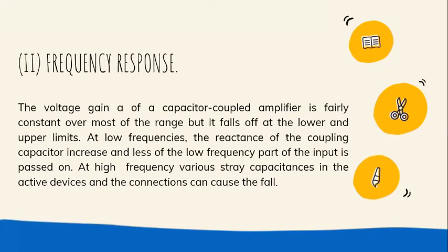At low frequencies, the reactance of the coupling capacitor increases, and less of the low frequency part of the input is passed on. At high frequency, characteristic capacitance in the active devices and the connections can cause the fall-off.